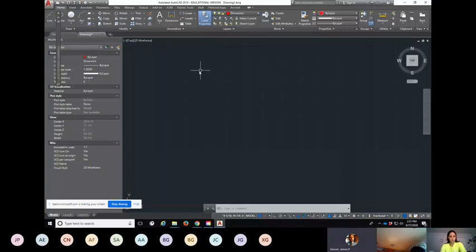That way I can change my layer and I can draw on my layer. Now my line type is thicker there. The more you zoom in, the thicker it'll show you. The more I zoom in though, the longer it takes me to get there. So your layer property, you can open that back up.